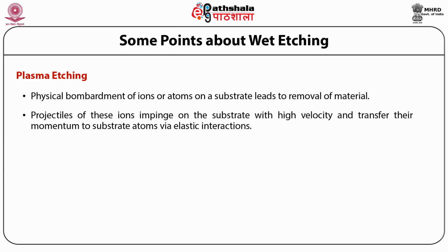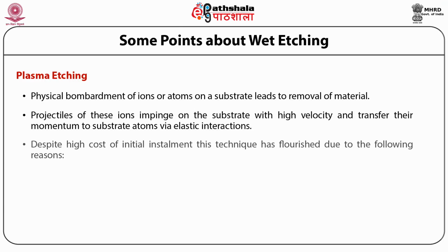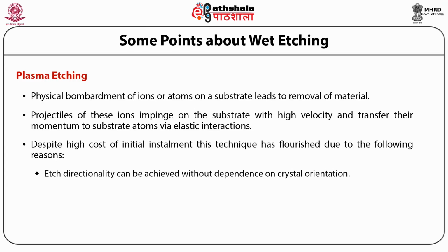Plasma-assisted etching has been rapidly used in recent years. Despite the high cost of initial installation, this technique has flourished for the following reasons. Etch directionality can be achieved without dependence on crystal orientation.